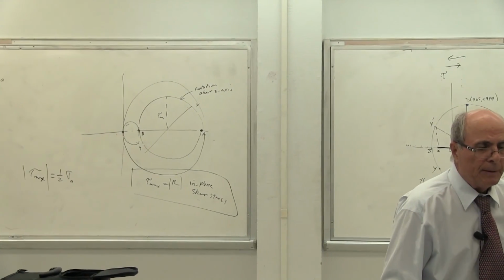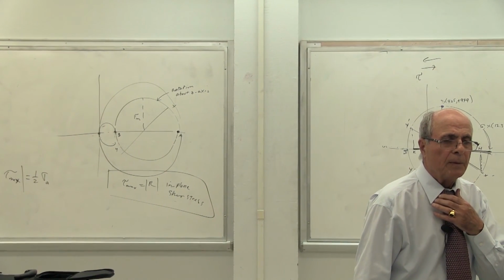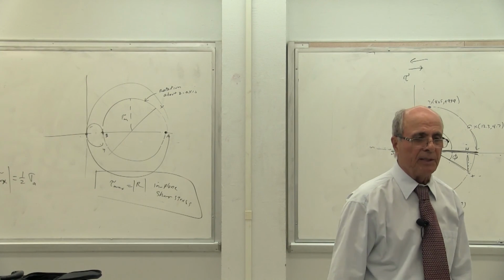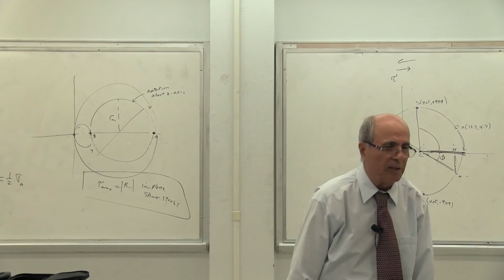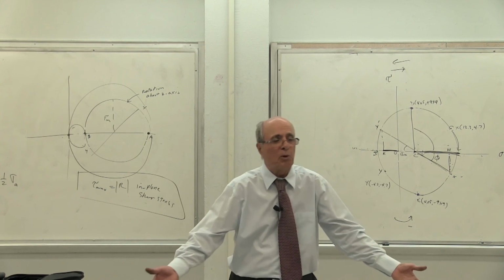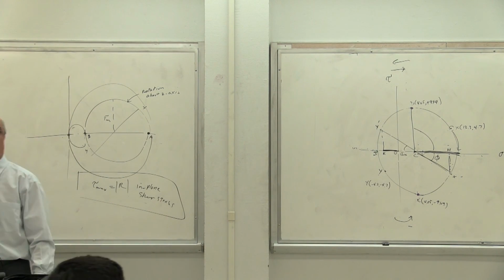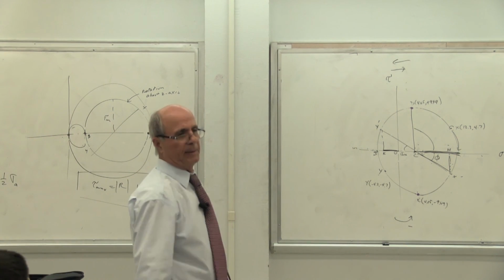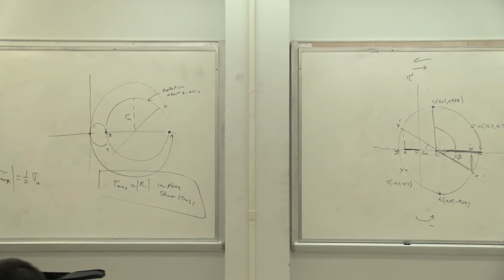Yes. I was just going to ask, so it's probably getting ahead, but do the 3 axes always have to be on the same line? Yes, because they're all sigma. They are on the same line always? Yes, because it's pure sigma. Right. Because they are pure stress, no shear. You are talking about the axes here, the principal axes. Yes. ABC doesn't have a shear. Remember that? Yes or no? Okay.